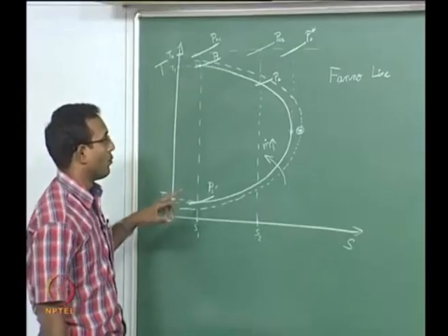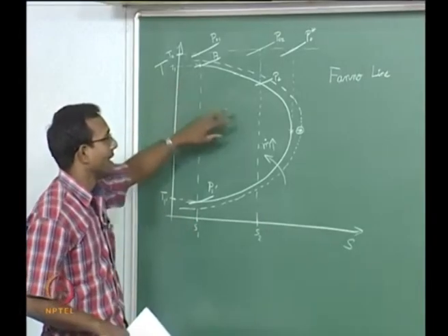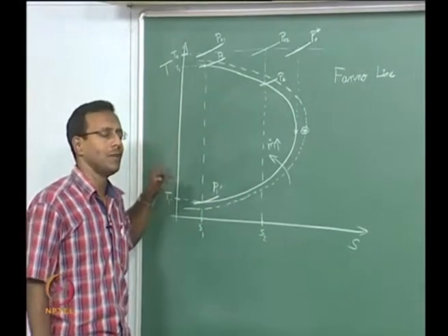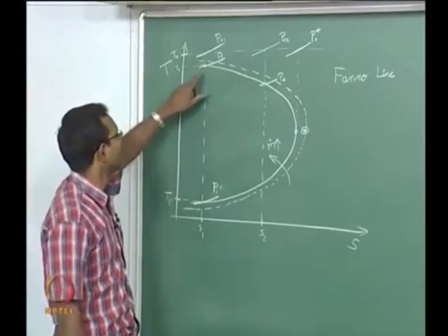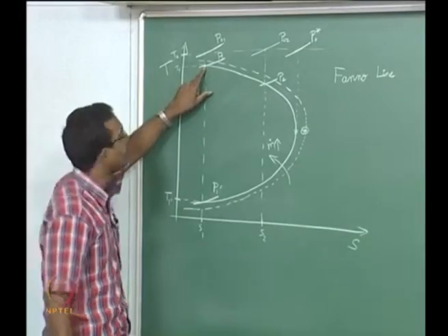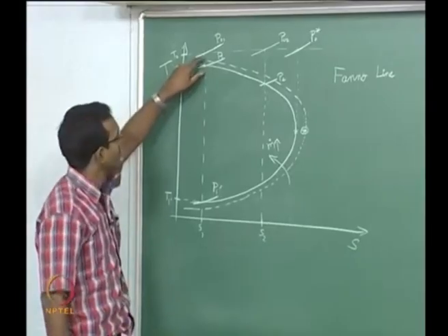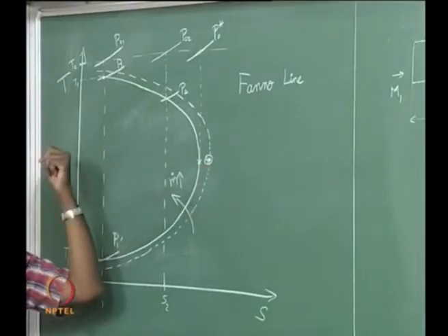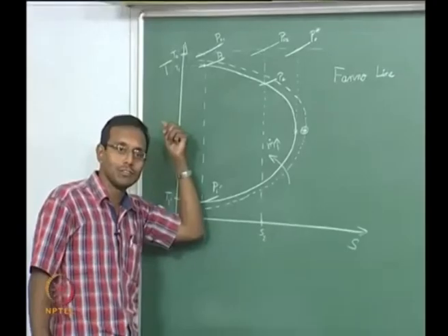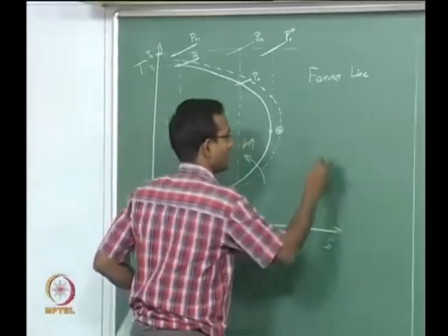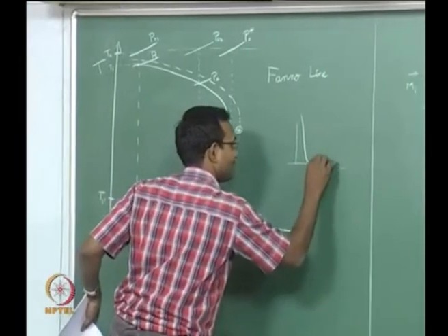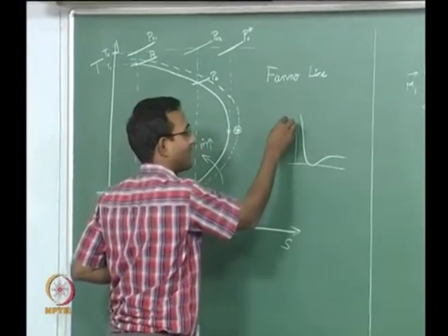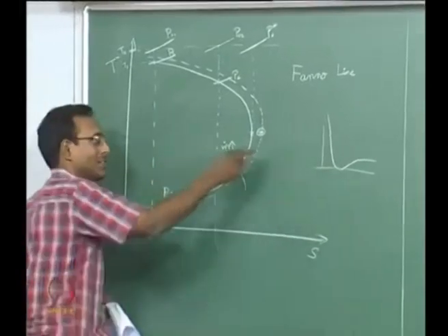So now what happens is, if I change my L star to be a little higher, length to be higher than the L star, then the solution jumps from this curve to the higher curve such that now it is all matched, and if I start from a lower Mach number, what happens to my L max subsonic solution? It will be higher. How do I know that? We just saw the plots, right? Plots were like this. If I decrease my Mach number, my f L star by d increases further. We keep f and d constant, so L star increases.